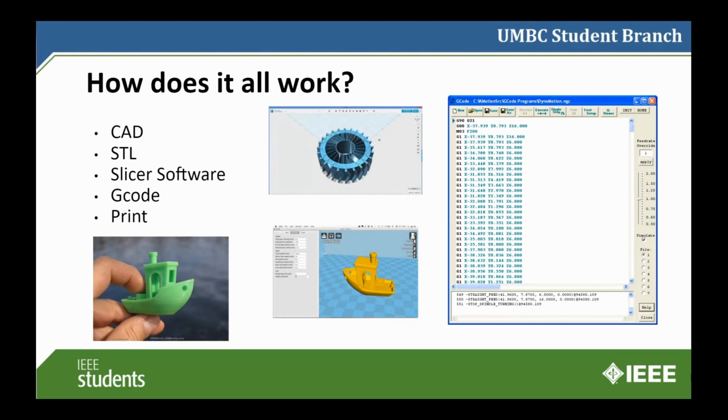After you slice the entire part, you press print, and then the information is uploaded into the printer, and the printer goes through and enacts those instructions. What you can see here are just coordinates. It tells the printer exactly where to go and how much filament to extrude, and it'll give you an estimate of how long it'll take depending upon the software.